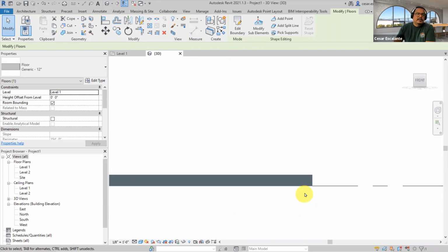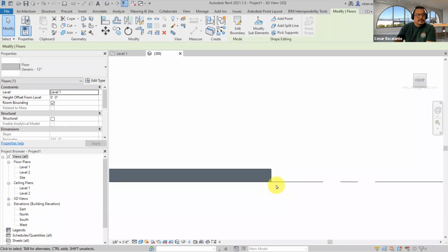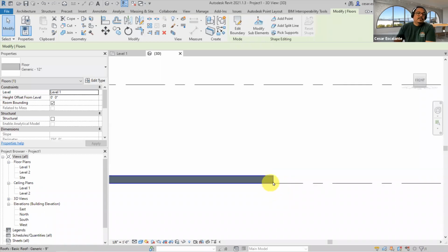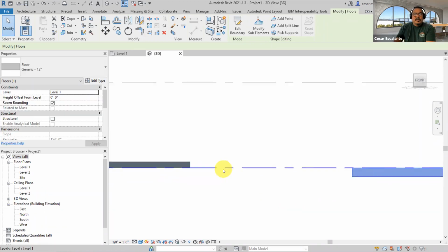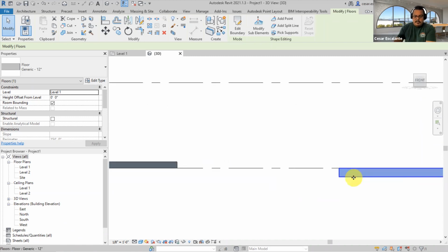And this makes sense because when you define roof, you maybe want to define the top of steel. Top steel is usually the bottom of the roof. And so if this is going to make a difference in the way you make decisions of the building, you can choose one or the other.